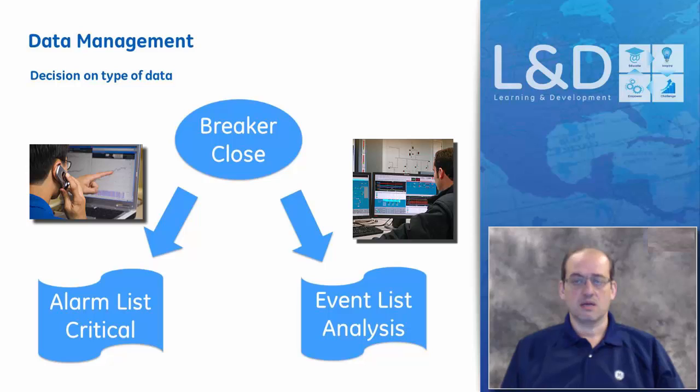So one of the main jobs in a substation design is to make sure that you list all the alarms and you list all the events that are required to be communicated to the central management system. Sometimes this is referred to as the point list, the tag list, or the point tag list. That's specified by the central management system and is given to the programmer of the main concentrator in order to make sure that the concentrator in its turn is doing the right job.